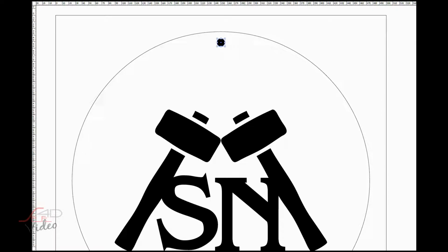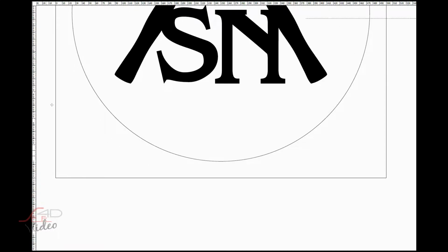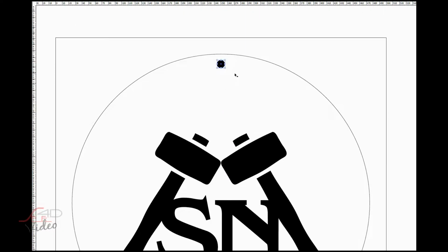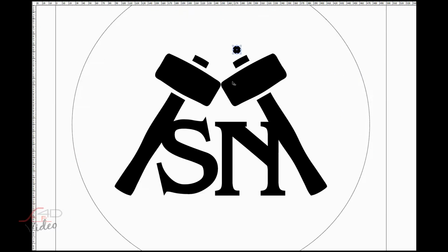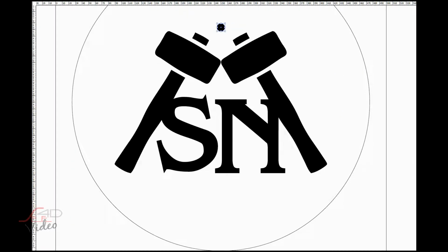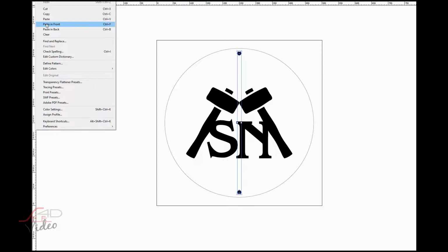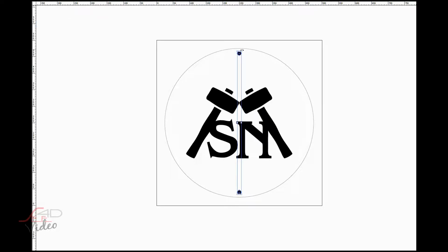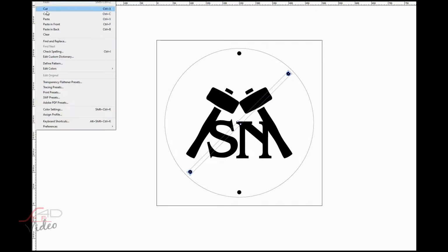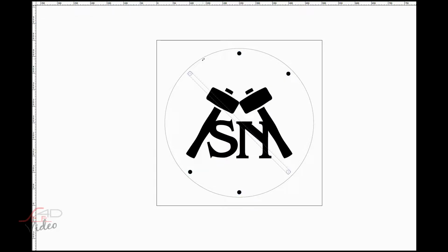When you're designing something that will be cut out from plywood or sheet metal, you must be careful, if you're using fonts, to use the appropriate fonts. You can Google the stencil fonts which are intended for this kind of procedure, and if you're using standard fonts, then you must be careful to modify some letters accordingly. Otherwise the cutouts won't look good after the process.